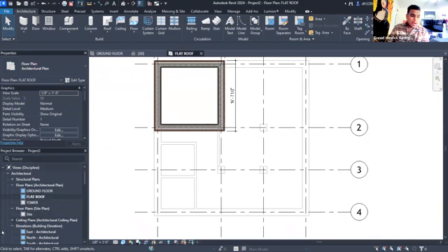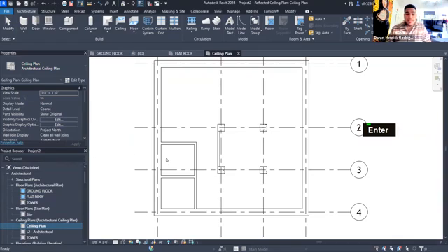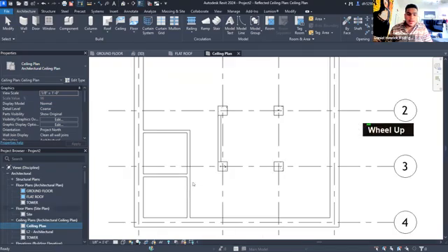So under the project browser, instead of a floor plan, we're going to go to ceiling plans, and we're going to click on L1. It didn't change its name, so we're going to change the name for it. And we're just going to call it ceiling plan. The first floor is the only floor that has ceilings in this project. Like I said, only trying to show you guys basics. The bathrooms are the only places that have ceilings. Everything else is just exposed roof. So exposed ceiling.